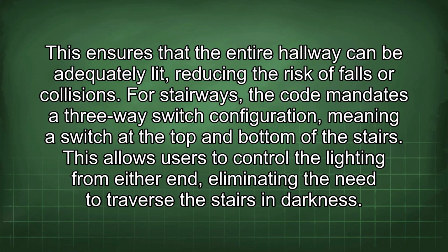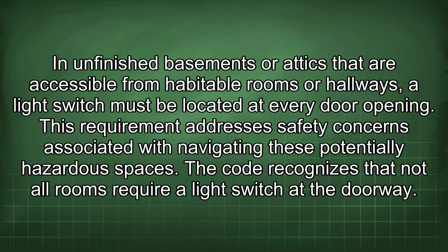For stairways, the code mandates a three-way switch configuration, meaning a switch at the top and bottom of the stairs. This allows users to control the lighting from either end, eliminating the need to traverse the stairs in darkness. In unfinished basements or attics that are accessible from habitable rooms or hallways, a light switch must be located at every door opening. This requirement addresses safety concerns associated with navigating these potentially hazardous spaces.